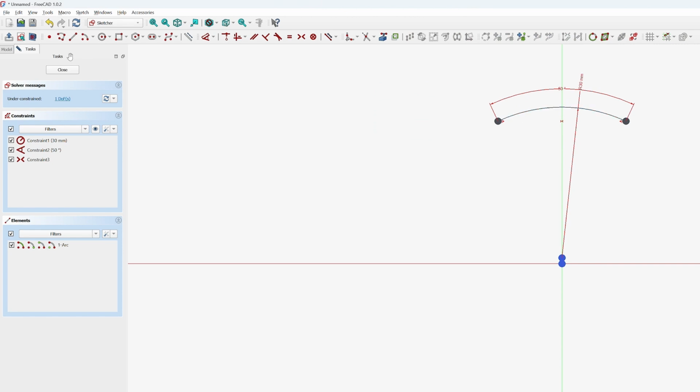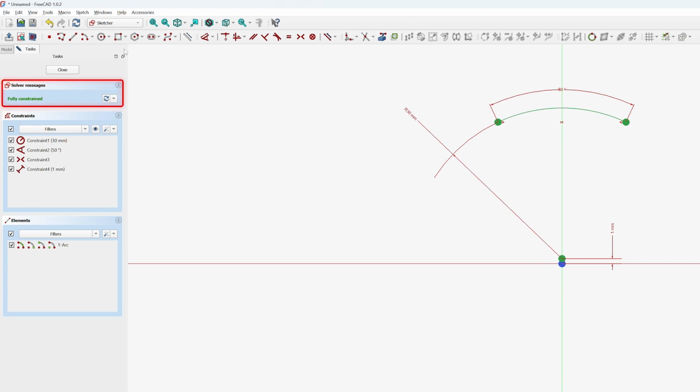So here you can see still the arc is not completely constrained. So let me put one more value here. Maybe I can choose the center line. Now let's make it fully constrained by providing a coincident constraint here. So I'm gonna make this point coincident to our center of XY axis. Now let me give the dimension value here. Now here we can see with the help of the following dimensional as well as geometrical constraints, we were able to fully constrain this arc. Let's talk about the next variant here, which is arc by 3 point.